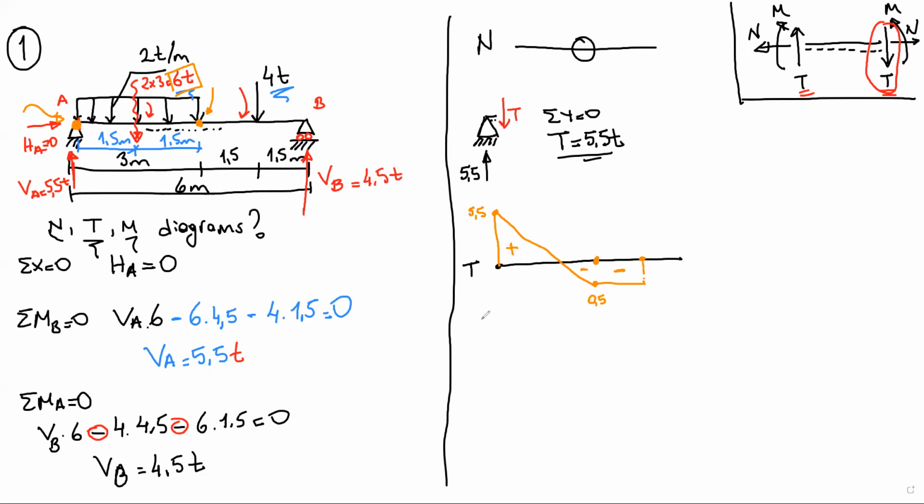So we are now where? Here. We have a point load. We have to take into account the point load on our diagram. What was the rule? If there is a point load on the structural system, there will be a sudden change on the shear force diagram. This was the rule. Again, please take a look at that table. Okay, where am I? I'm at this point. My shear force value is at this point minus 0.5.